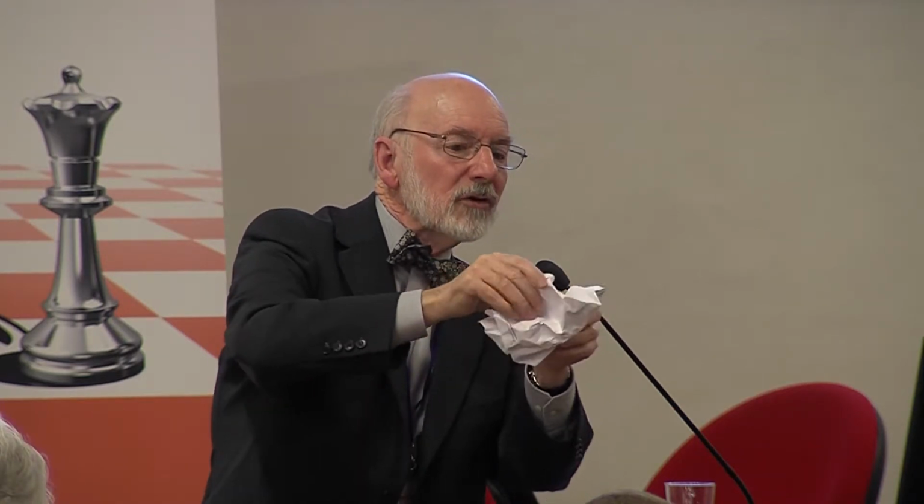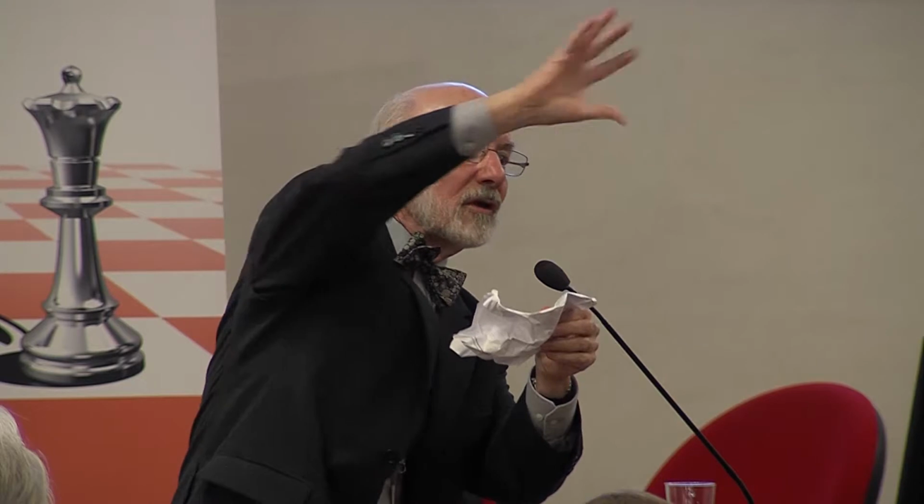When the metal finally stops moving, this will now start to open again. And there are all sorts of interesting mechanisms which reopen the crack. And fold by fold, it opens. And each time a little fold opens, and all of these things are opening everywhere, right through the metal. Each time it opens, the properties come down. And then it opens another part, properties down. Opens more, the properties down. And so in our thick sections, we have minimum properties because this has plenty of time to open.